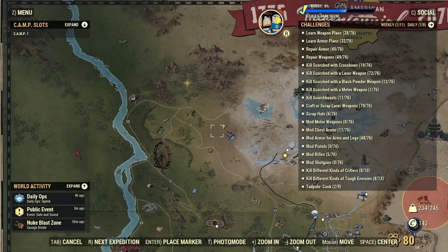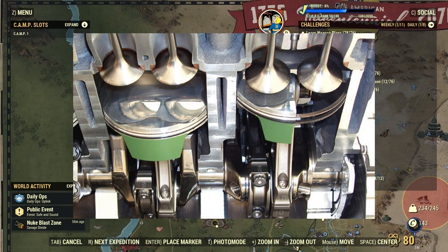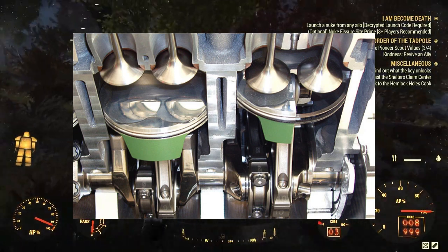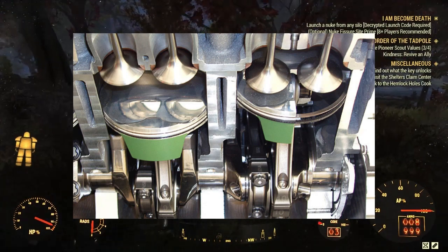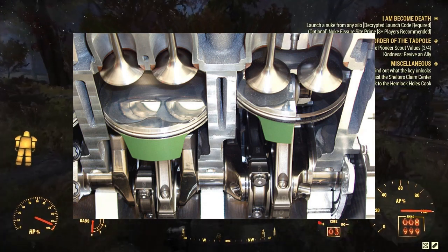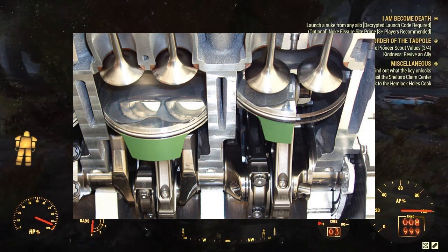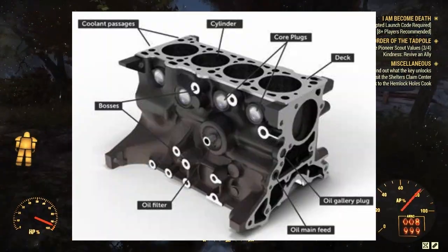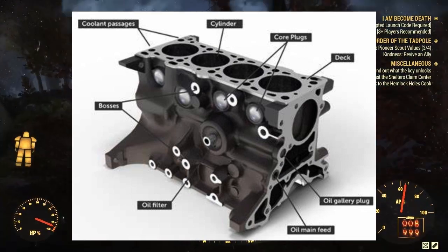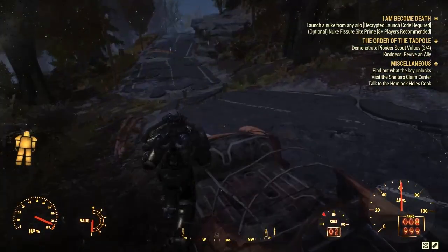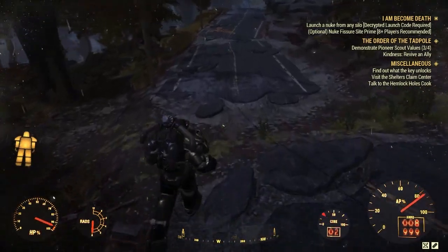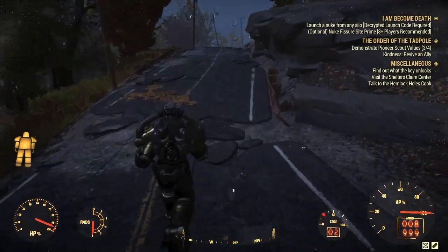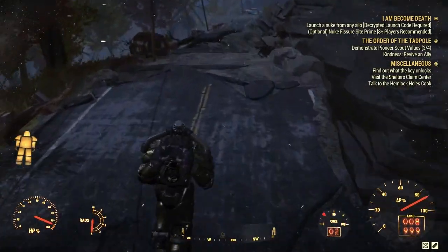The piston has to fit within the hole on the engine block, because the engine block contains holes where the piston actually slides into. The fit cannot be perfect, because otherwise it would take too much force to actually put it into that hole on the engine block.